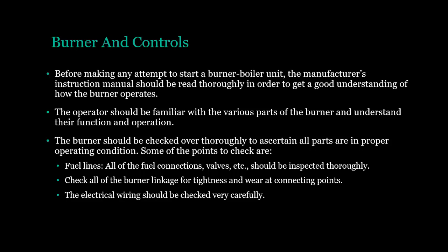Some of the points to check are: fuel lines, all of the fuel connections, valves, etc. should be inspected thoroughly. Check all of the burner linkage for tightness and wear at connecting points. The electrical wiring should be checked very carefully.